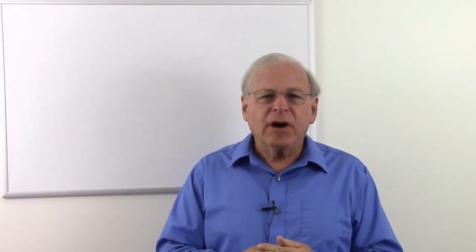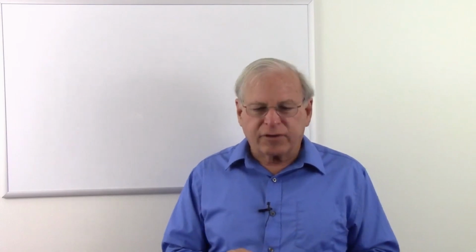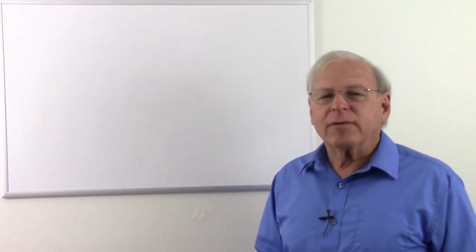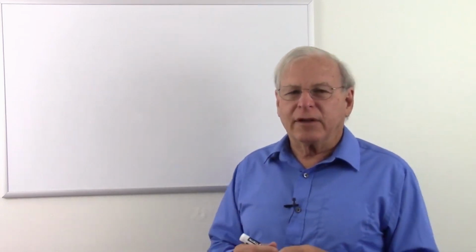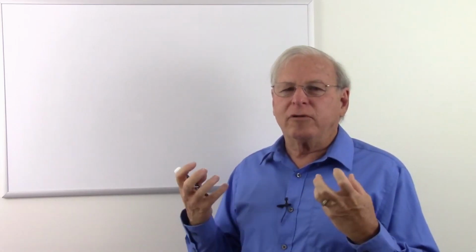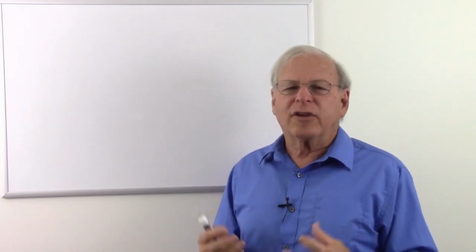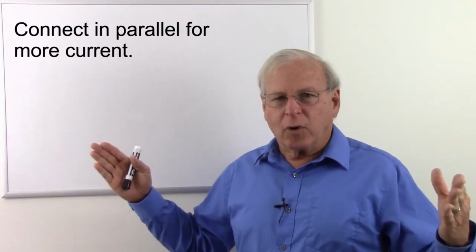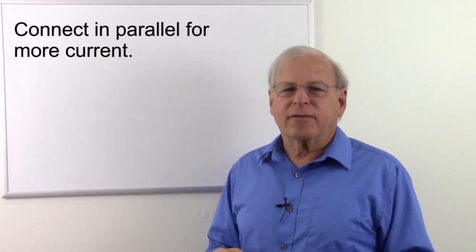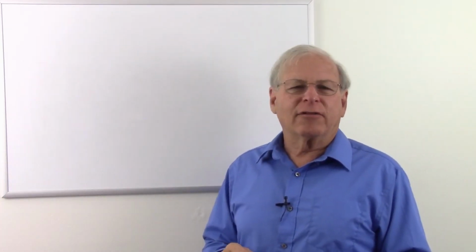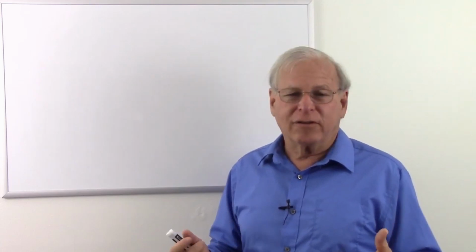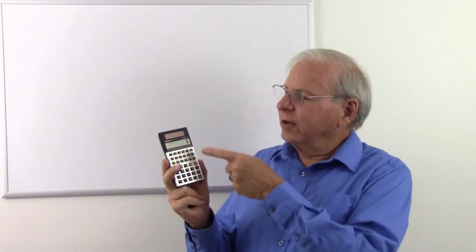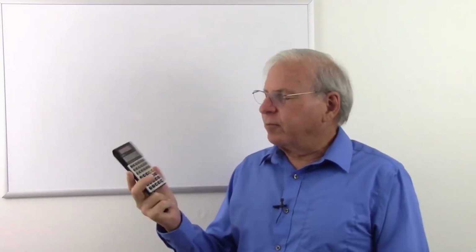Now let's look at some photoelectric devices. First thing we're going to look at is a photovoltaic. These are something becoming fairly common because the sun falls on them and they produce voltage. I think one cell produces about half a volt. You can put these in series and get more voltage, make more area and get more current. And of course, you may even have these on your house as we speak, or other devices. I have a calculator that, well, here it is. Little calculator with a solar cell right there. Never have to put a battery in this.